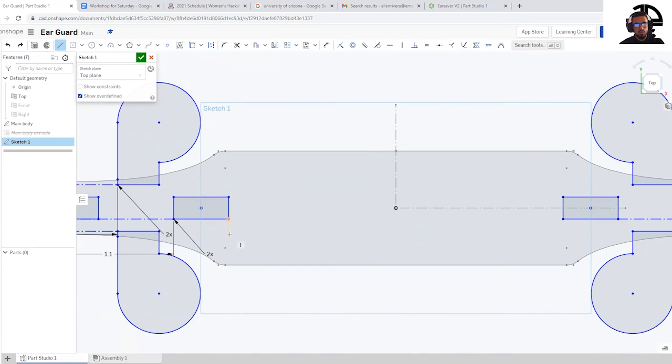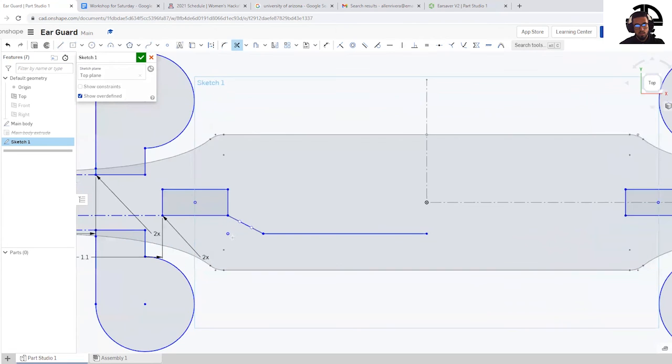So I'm going to just make it parallel, go to the origin, make it horizontal, evenly horizontal. And I'm going to want to add a spline to here, from this line to this line. You can just eyeball it, doesn't need to be perfect. Set that. You can trim this line. So we're using the trim option again. Okay, and hit escape, highlight that point, delete.